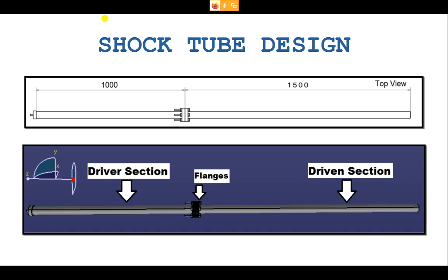What we decided is we went ahead and found what materials can be used for these two sections. Initially we thought about metallic pipes and metallic flanges. Later we thought that metals will be costly. Why do we not go with a plastic kind of material? That is where we thought HDPE will be fine, which is ultra light in weight compared to metals. If you see the strength, it is of comparable strength, and for manufacturing, machining or fabrication processes, plastics are always easier to handle. That is why we decided to go ahead with HDPE material itself.